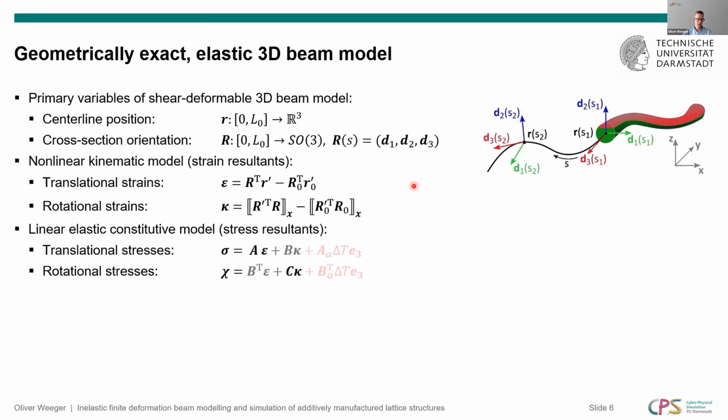Now, typically in these 3D beam theories, a linear elastic constitutive model is used where the strain measures are mapped onto stress resultant measures.